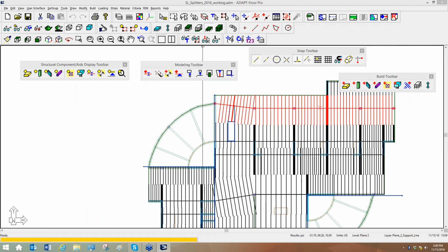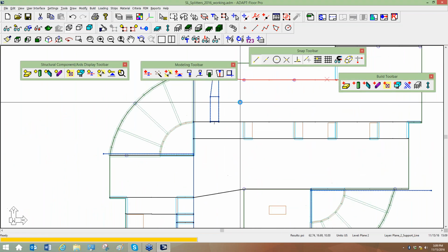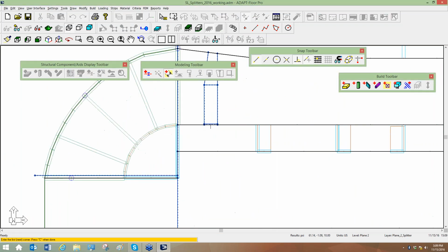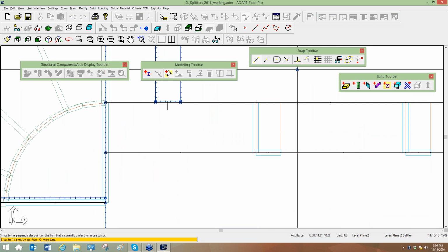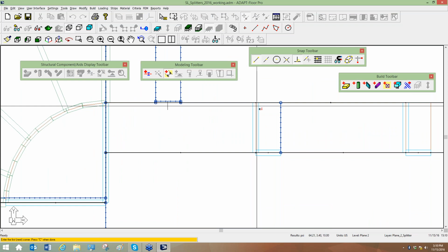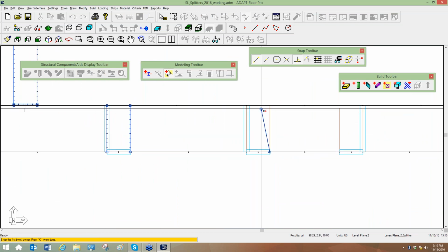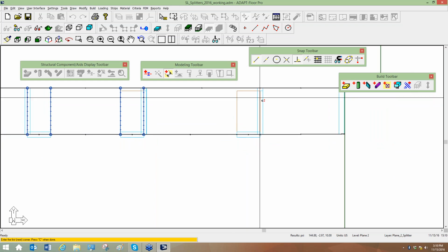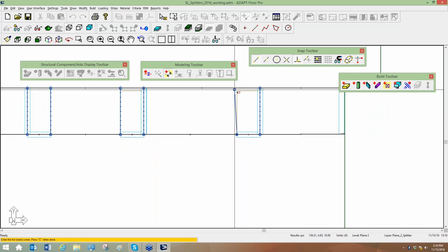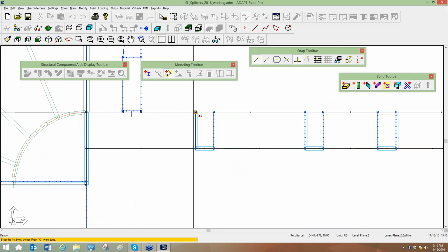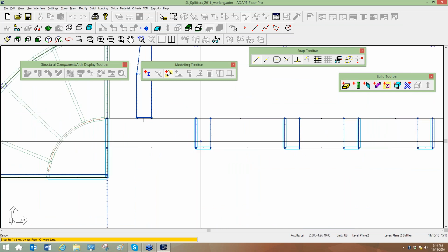Now I'll go ahead and do a few more here just for the sake of being able to see how these would be input. So I'm still creating X direction splitters. I'll keep emphasizing snap tools are very important. Now I'm going to input these a specific way, and then I'm going to show you that these are essentially useless if we don't close them off. So here I have splitters, but there's no splitter that closes off the top and bottom of the opening.